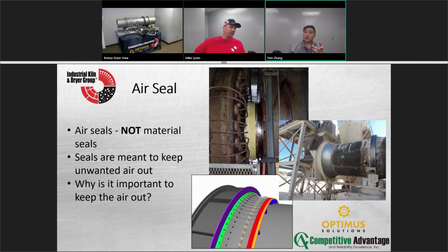So, the thing is, if you get air from the outside, you're going from 75 degrees or whatever the ambient is up to that temperature, 1,000 degrees F, 2,500 degrees F. You're heating unnecessary amounts of air. And also, we talked about last time what it does to the material. The chemical changes, yes. Because if you're looking at 1,600 degrees to change from limestone to quicklime, and you go from 1,600 to 1,550, maybe you're not getting that anymore.